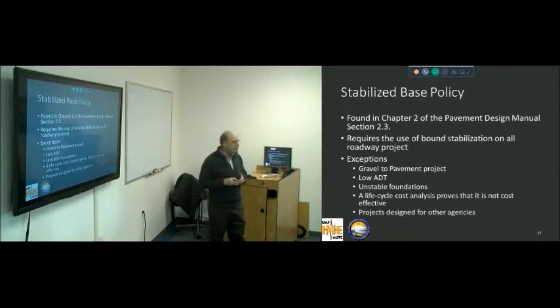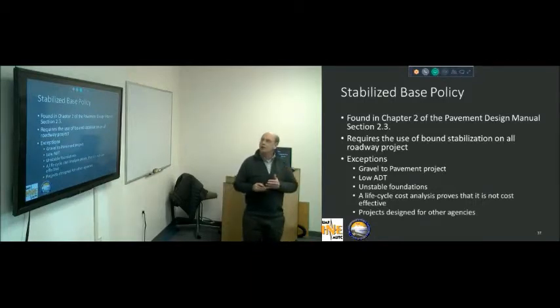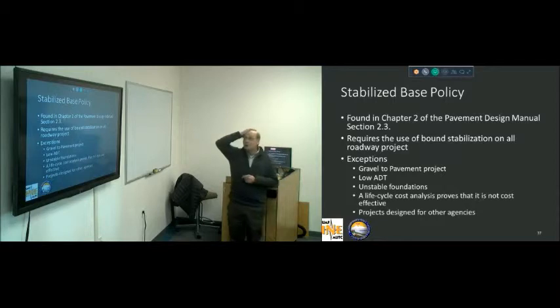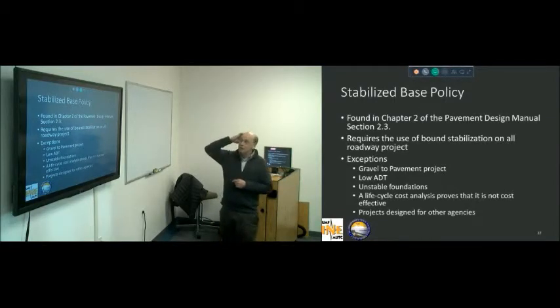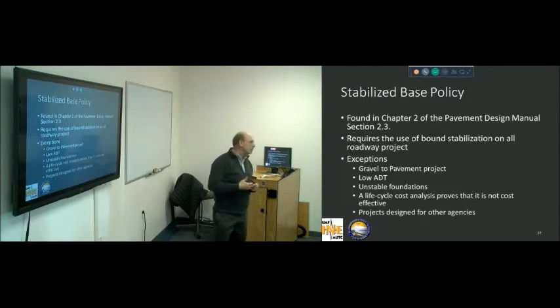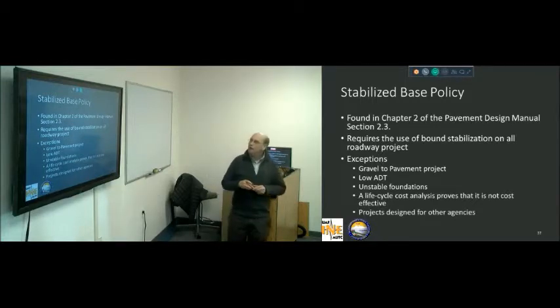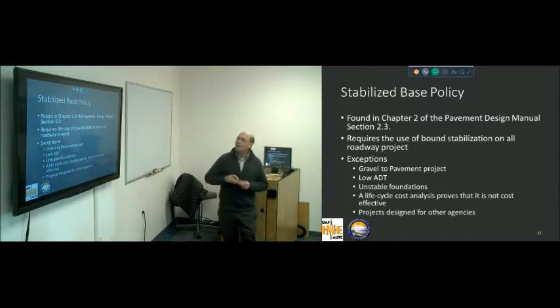This came out of frustration of our then chief engineer, who was finding that a lot of folks were hoping that we keep the fines content down. So he said, okay, we'll solve that problem. We'll just stabilize it. Stabilize it means a number of different things, a number of different options here. The full depth reclamation and all its forms in there. Basically what the book says, if we can get a modulus of 85 KSI or better, it's considered stabilized.